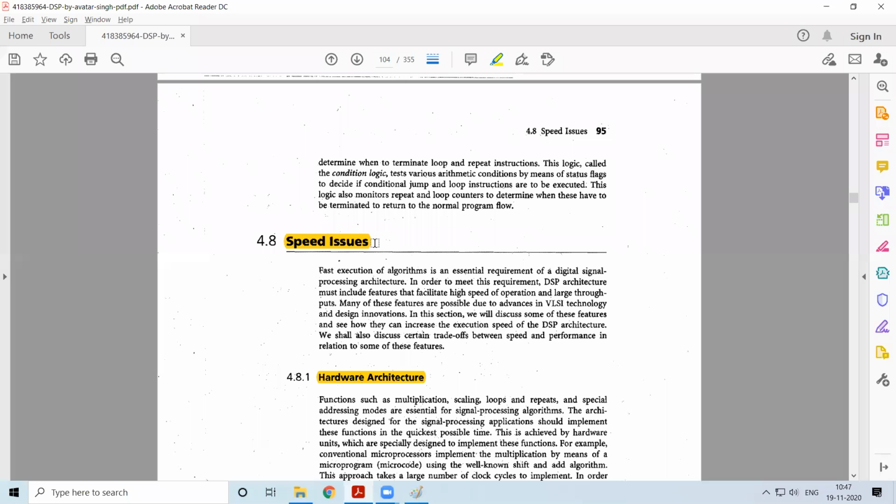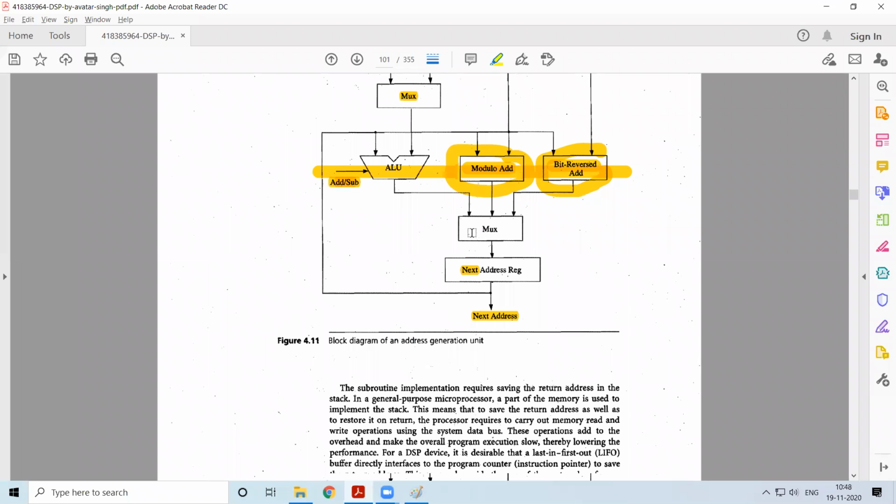Similarly, other kinds of hardware are also utilized. That is, the hardware architecture. One specialized architecture is the Harvard architecture. So in Harvard architecture, what do you have? You have separate memory for program and separate memory for data. If you remember, with two separate memories, at a single time we can access the instruction and then the operands. If two operands have to be accessed, you can provide more than one memory for data and one memory for program. So that is what we observe.